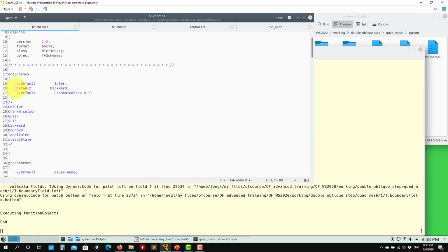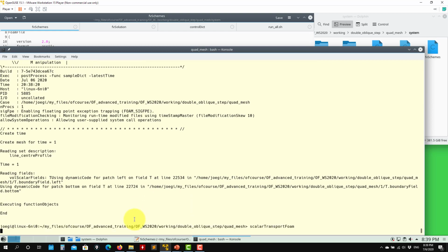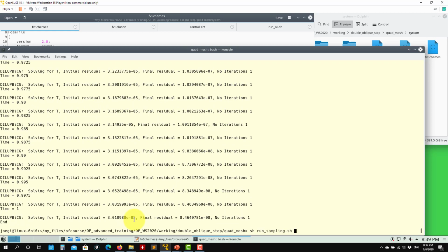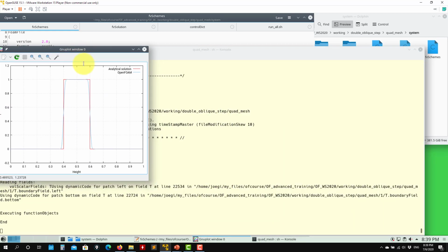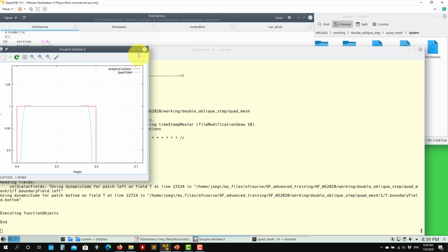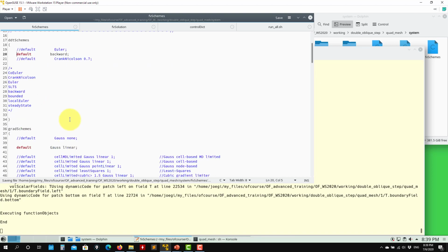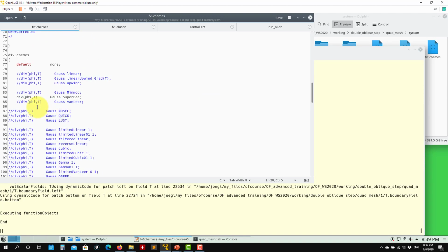If we go here now, Crank-Nicolson is also a second order accurate method, but again it is unbounded. If I go with pure Crank-Nicolson, let's see what we have. Very similar behavior. It's becoming a little bit unbounded there. So what can we do to stabilize this one?